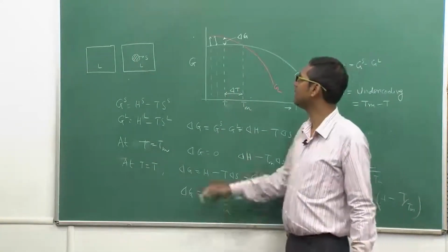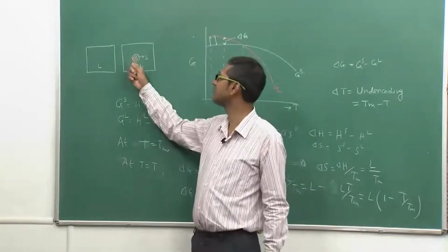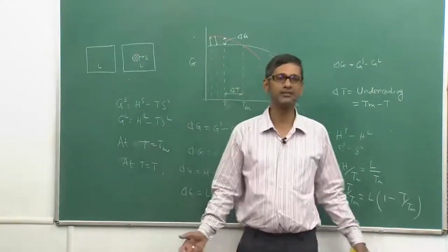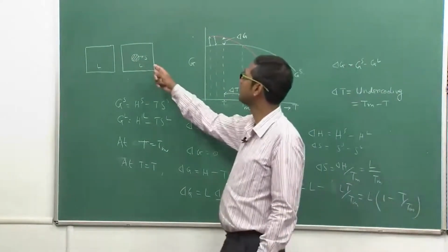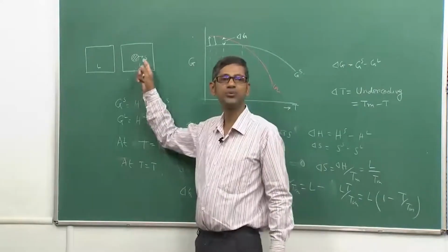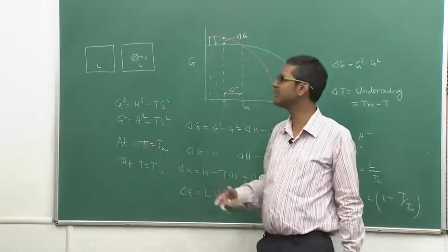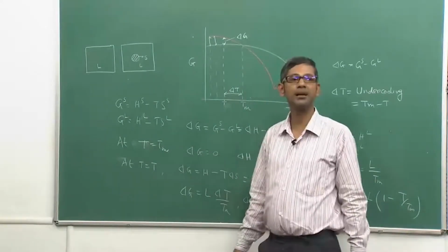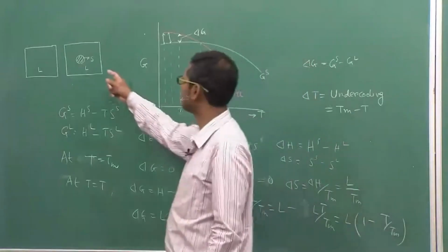On the other hand, liquid is a completely random structure, and because of that structural difference, even if there is no chemistry difference for pure metals, this leads to an interface between these two phases. This interface, by virtue of its existence, will have certain energy because it has broken bonds at the interface.